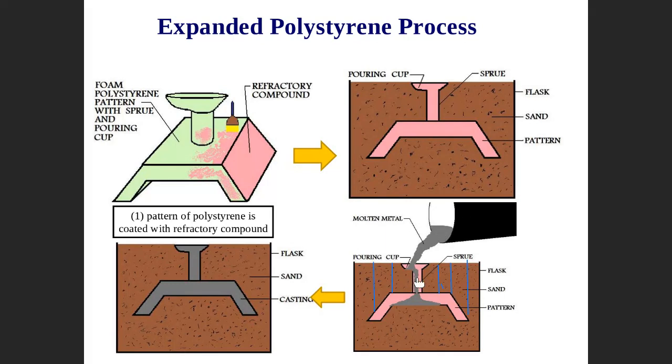Okay, then when you put liquid inside, this liquid will replace the foam. Foam will be evaporated and move out, and liquid will fill the place, replacing the foam. Then finally, all the cavity is filled with the liquid. Finally, you destroy the mold, you take the part out. That's why we call it lost foam, because foam will be lost, evaporated. We will not have foam anymore.